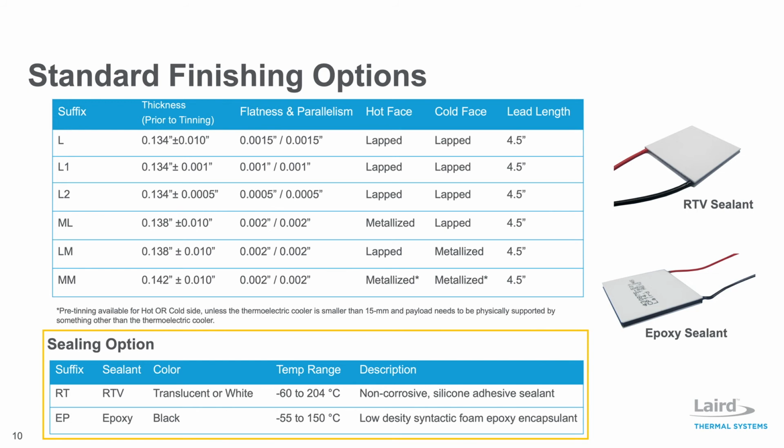Epoxy is an effective barrier to moisture that exhibits a usable temperature range of minus 40 degrees C to 130 degrees C. When cured, the material is completely unicellular and therefore moisture absorption is negligible. Epoxy material exhibits a low dielectric constant, low coefficient of thermal expansion, and low shrinkage. Epoxies are ideal for applications requiring long life expectancies.